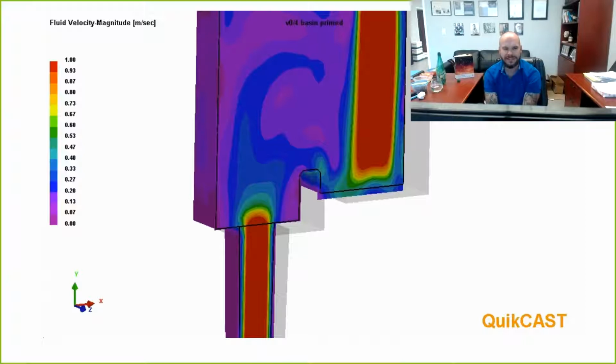And what I mean by that is any ladle slags that are forming in the edges of your ladle that happen to make it in and fall off into the stream are going to hit that basin, the basin is full, and they're going to stay floating on that surface. And any that make it subsurface are going to have a chance to float out right away because they're not getting pulled down by a stream that's sucking them right down into the sprue.